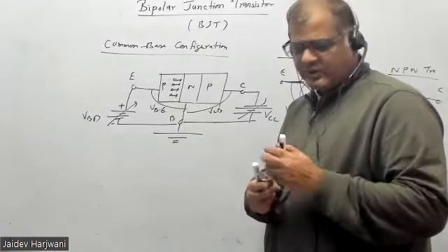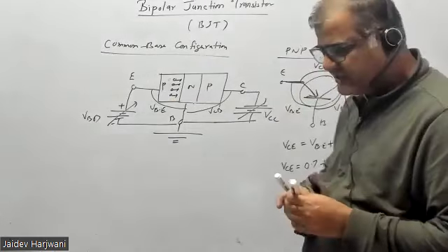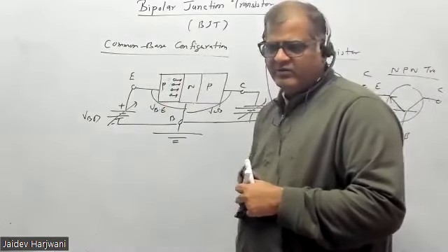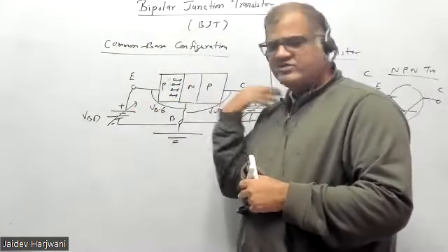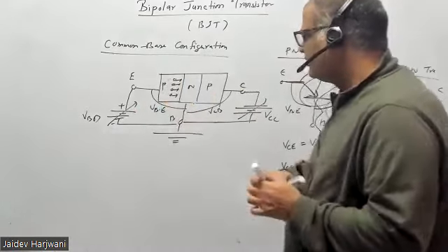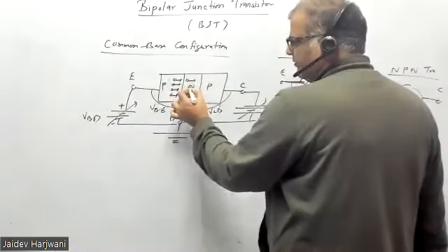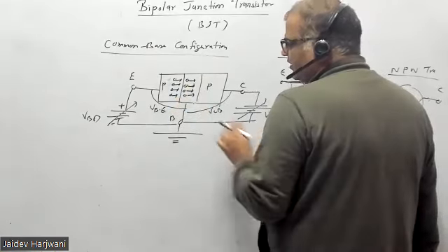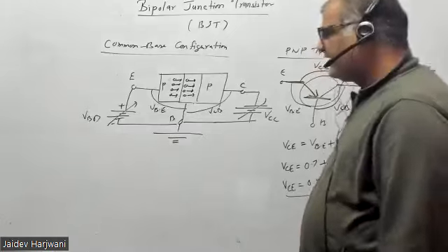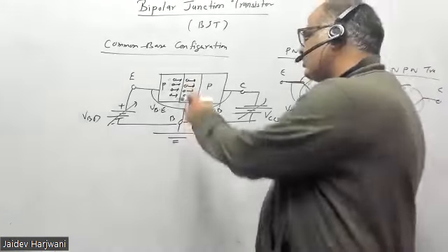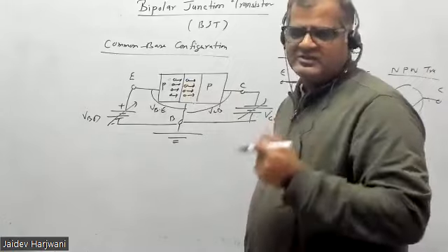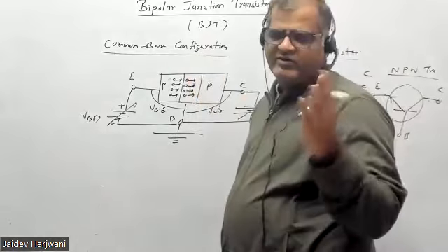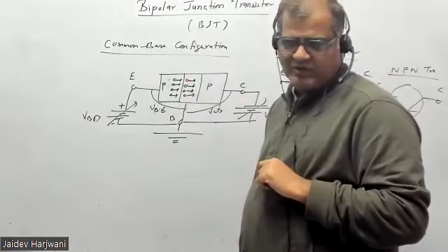In equilibrium the gate is closed, okay. And why it is closed we have discussed in equilibrium PN junction. But now you're applying forward bias, that means you are bringing the barrier down, or you're slightly opening the gate. So again the diffusion will take place and these holes will reach the base region, okay. Say base, these holes are coming into the base region. Now this base is very thin and very lightly doped. So these holes cannot recombine with the electrons because this is n doping, and the doping is very small. So we don't get any loss, only very slight loss of holes, okay.